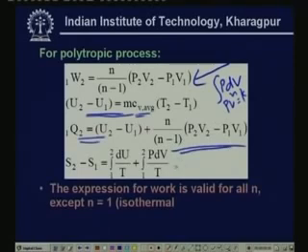And the general equation for entropy change in a polytropic process is given by this. This is nothing but the integration of the TdS equation. That means when you perform the integration of the first TdS equation, you get this kind of an expression, and depending upon the relationship between dU and T and PdV and T, you can find out what the entropy change is. For example, if it is an ideal gas, and you are also assuming that Cv is constant, then you can write this as Cv dT. Similarly P can be expressed in terms of T and V.